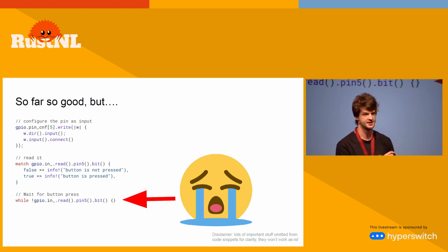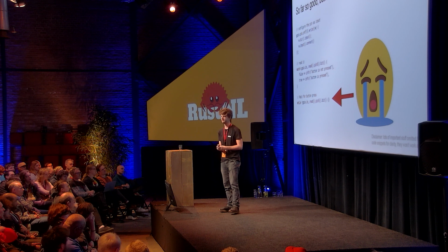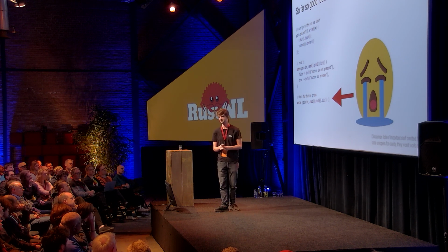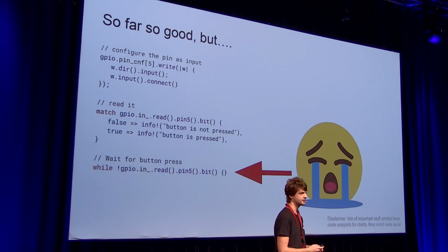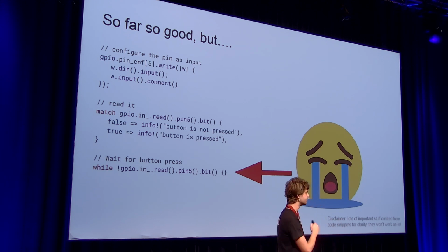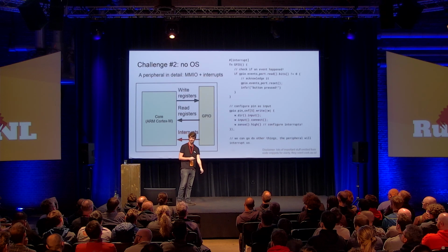But of course, this sucks for a few reasons. First reason is, while you're spinning here, you cannot do any useful work. You're just waiting, burning CPU time. And of course, it's also really bad for low power. If you build battery-powered devices, which I do, you don't want to do this because you're keeping your core on all the time. If you did something smarter, if there's nothing else to do, you could put the core to sleep, saving a lot of power.